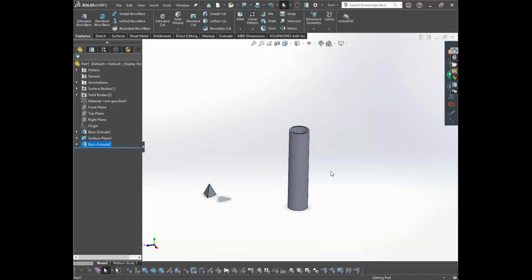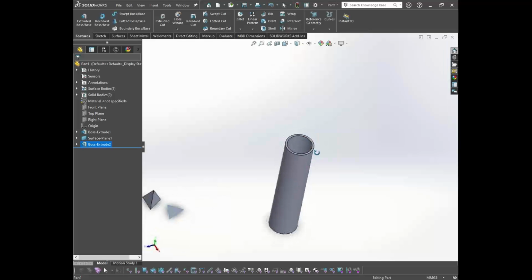Okay. So when our assembly consists of parts having uniform cross sections throughout the length, we convert them to beam elements. Or if we are considering structural members, like I-beams, C-sections, or a pipe like this one, I can tell the software to convert these into beam elements, which will save the meshing time.